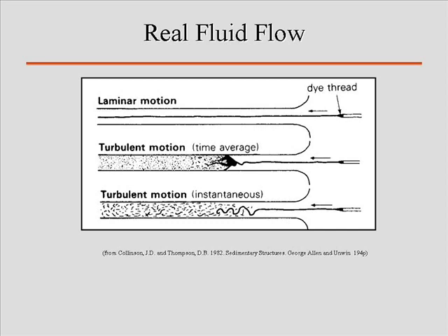And what you'll see is, in this case, water passing through a tube, and an ink blob is distributed here. All of a sudden, it will break up into its own pieces because you go from being laminar to turbulent. What controls that, however, is really, really hard to understand. That's why physicists turn to the idea of ideal flow. Realistically, you can have a situation that looks like this, repeat the circumstances exactly, and it goes turbulent. So there are some variables in here that are so finicky that it can change from one thing to another, which is why a lot of people start thinking, well, maybe it's chaos theory, right? There's some difficulty in doing all this, okay?